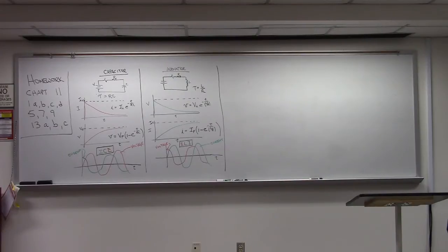How about your values? Okay, good, they are correct. All right, so now we want to adjust these here. Channel A is 5 volts per division. Channel B is 100 millivolts. Okay, channel C is 10 volts per division?